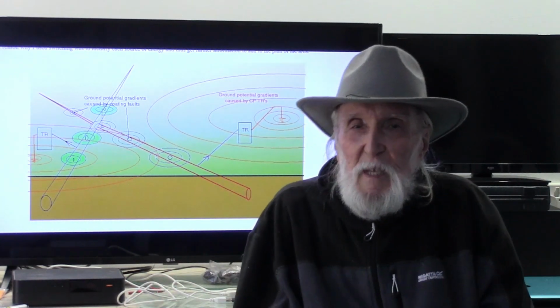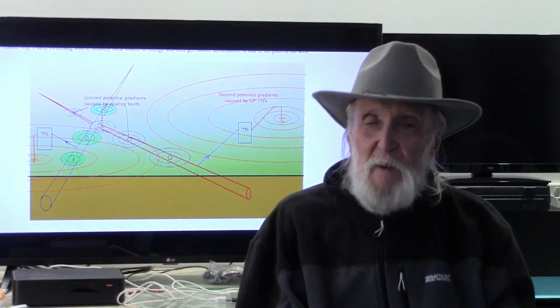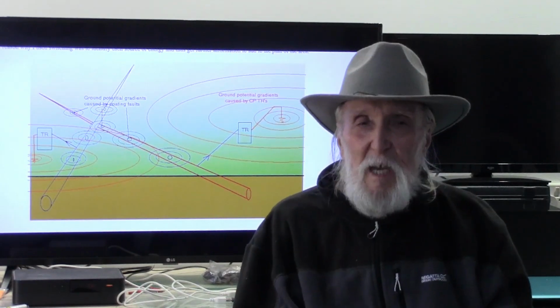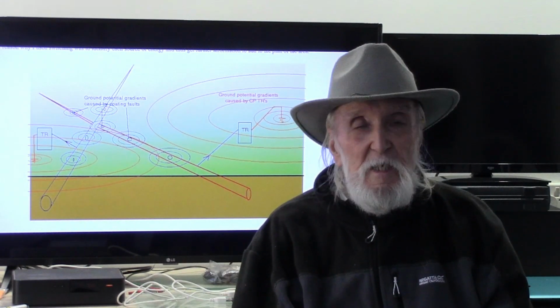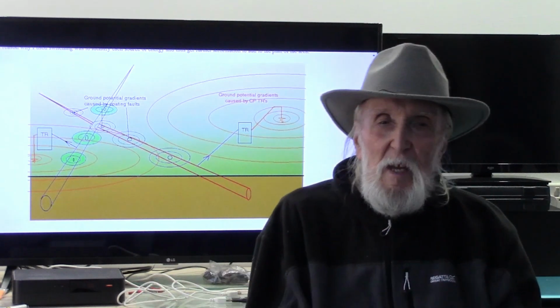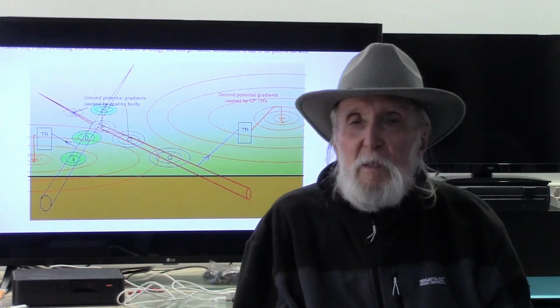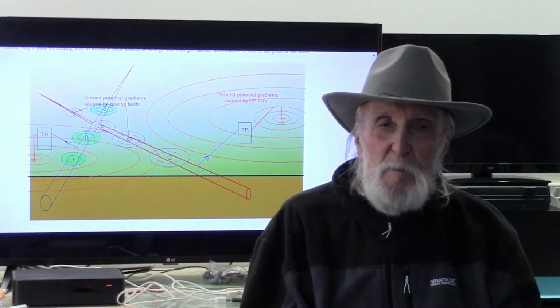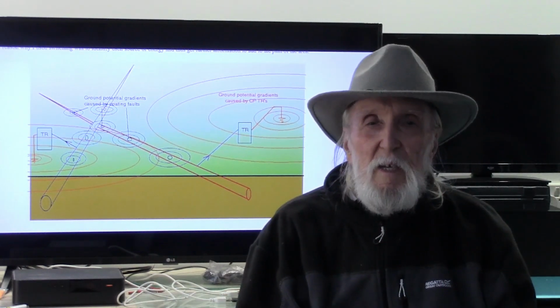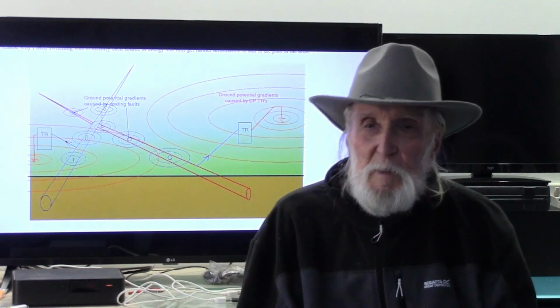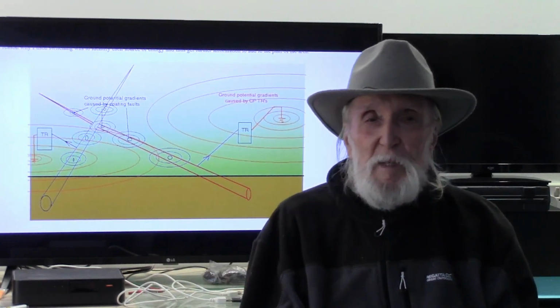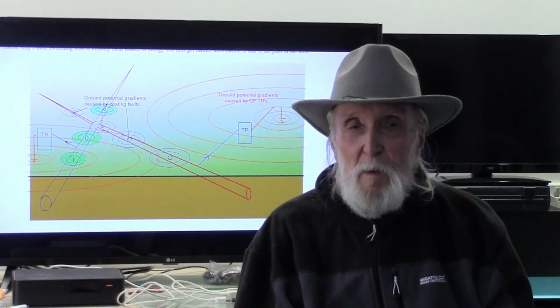This will show the exact paths of the various currents and the exact position in which to place the sacrificial anode in each case. It will allow us to see the performance of each anode and to balance the impressed current cathodic protection systems to reach a protected equilibrium.